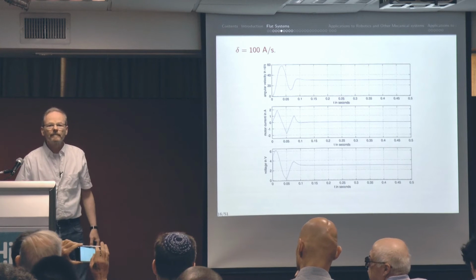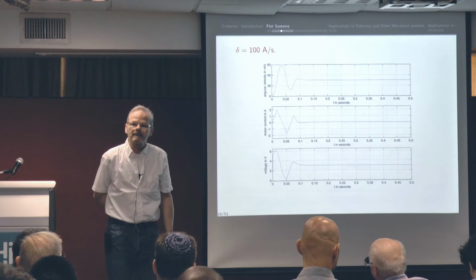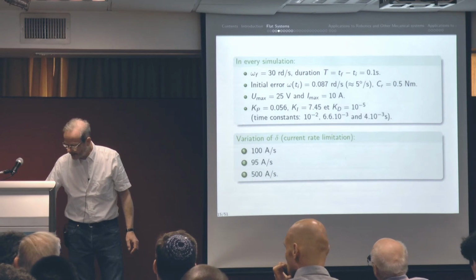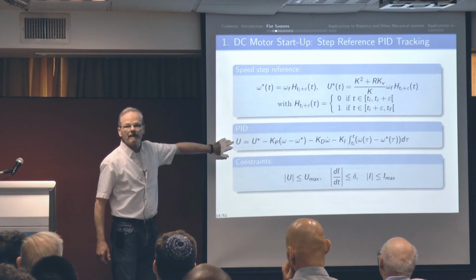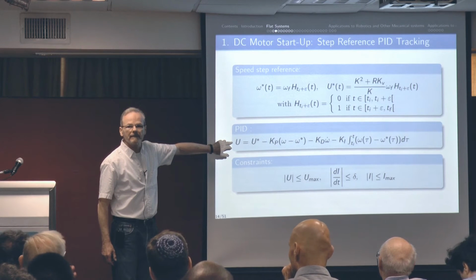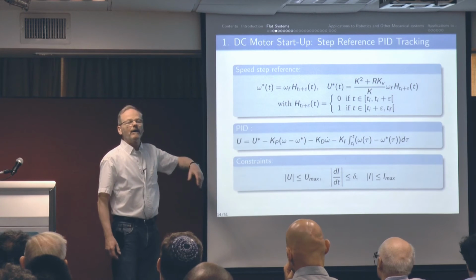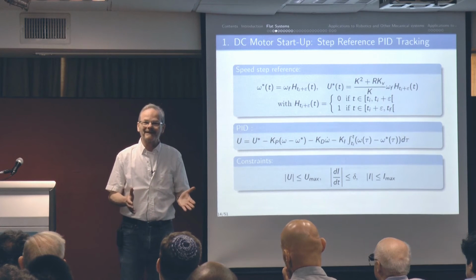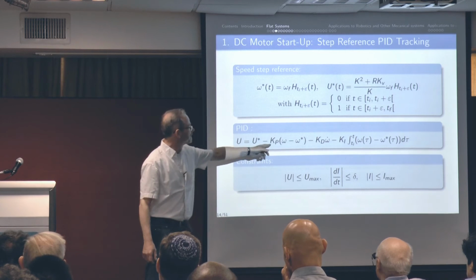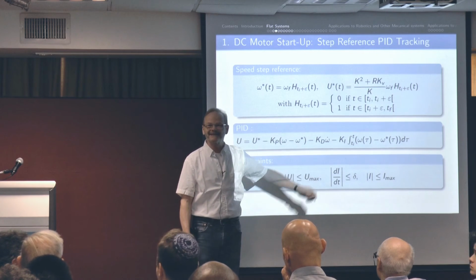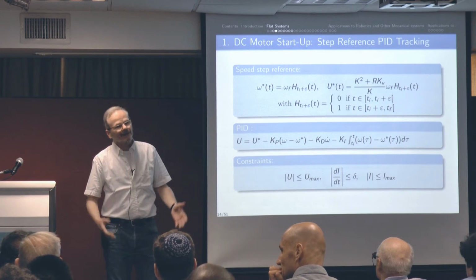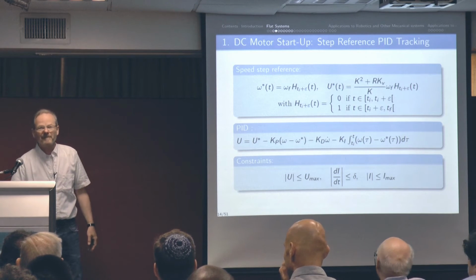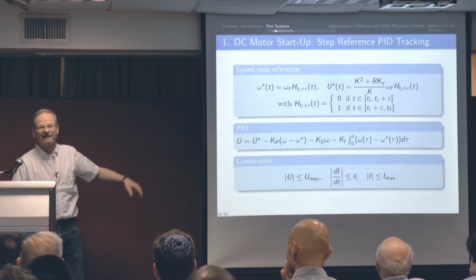The constants, are they the result of some optimization? No, no. It's satisfying this PID. How do you choose KP, KD, and KI? By very classical techniques, by tuning first the KP and then improving by KD and then experimentally, yes. Well, of course, it could be improved. I fully agree. But that's just quick and dirty job.